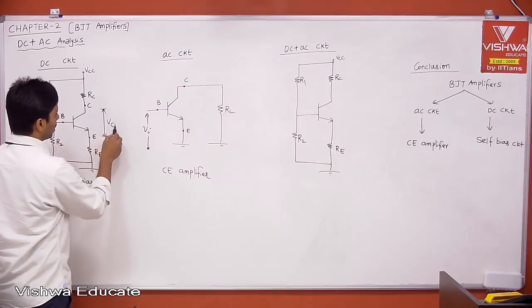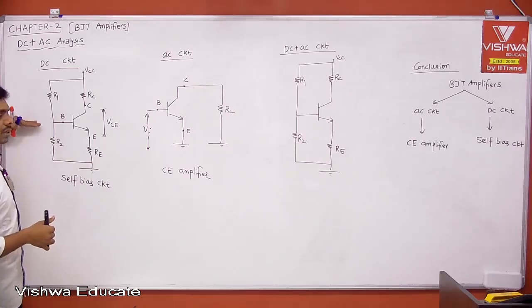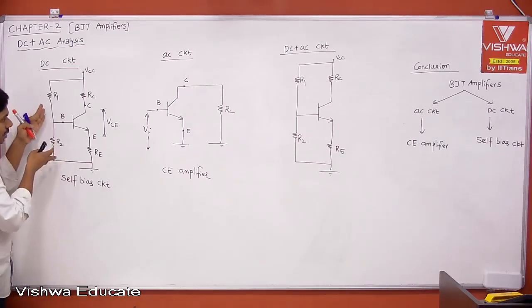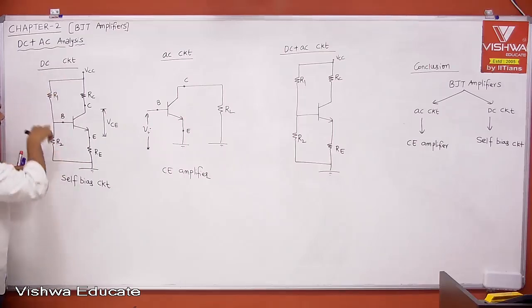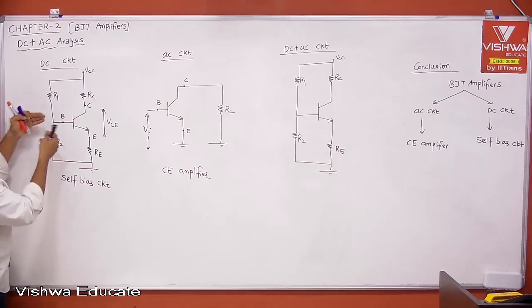It has some DC voltage. Then I need to apply the input signal here, right? Already it has some DC voltage, that is V Thevenin, R Thevenin, using Thevenin's theorem. That is V Thevenin, R Thevenin, which is what is defining your IB, right? Therefore now, how to apply the AC signal on top of the DC signal?